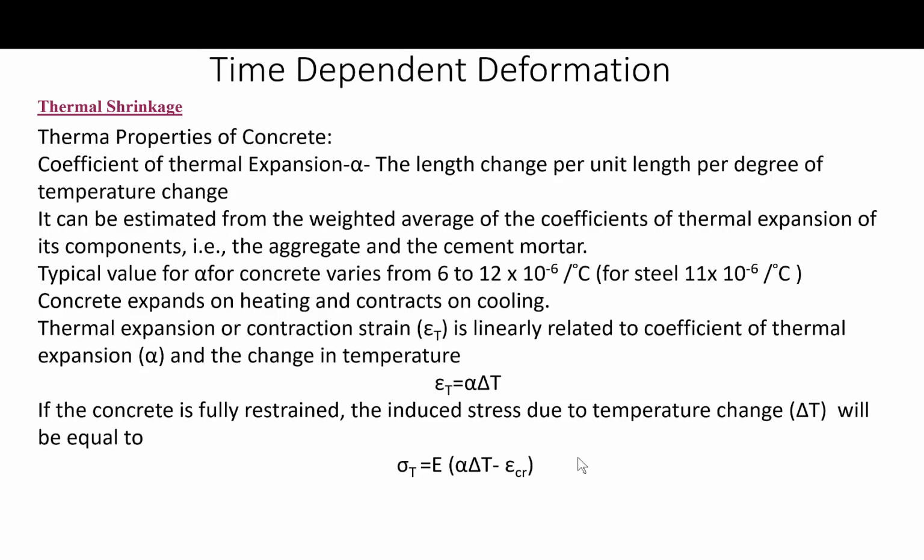I have seen many cases, especially in mass concrete in thick sections, where thermal shock could be a problem, where the construction teams were either lax, careless, or uninformed by their supervisors about such a phenomenon, and did not take enough care to insulate the concrete.